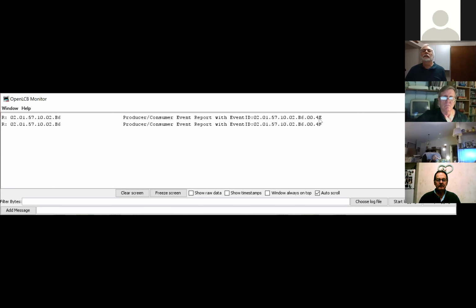And there's the event that says, hey, that switch just went down. So I'm throwing the switch up and down. I'm getting events. You almost always have events in pairs because, unlike a wire, which is continuously at one voltage or another and is continuously saying the switch is up, the switch is down, the light is on, the light is off, with this sort of thing you need 2 events. One to say it changed this way and one to say it changed back again. You always need a pair. Well, not always, but mostly.